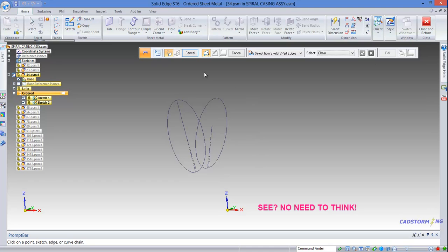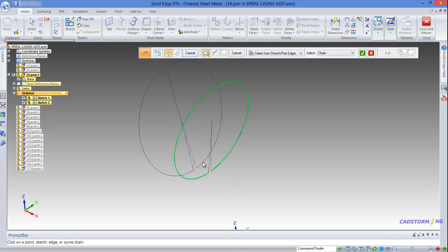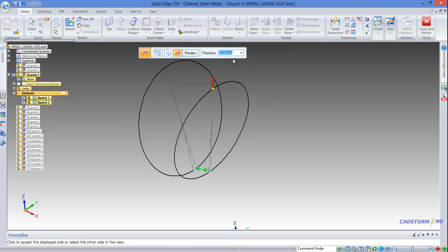Now radial menu, I have the lofted flange tool active. Select my first profile, and then I select the second profile, right click to accept first, then I select the second profile and make sure that the 2 starting points are correctly lined up, and then I just have to define the side where the material will be added.